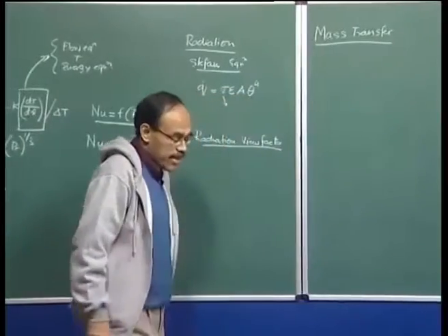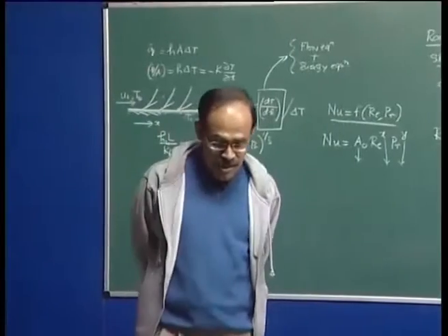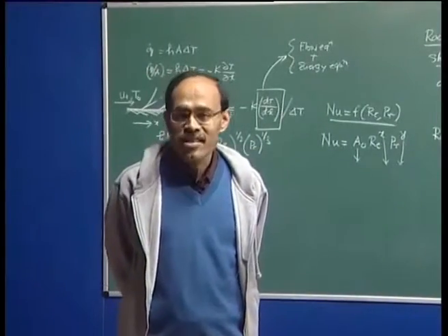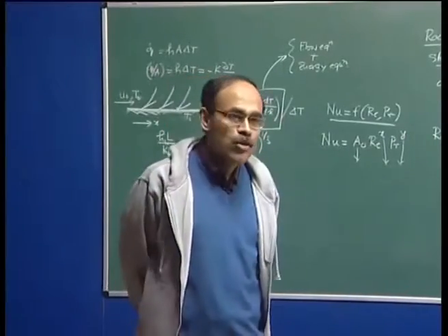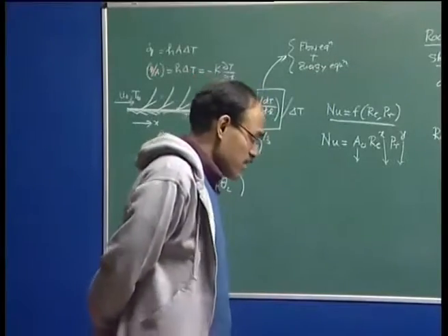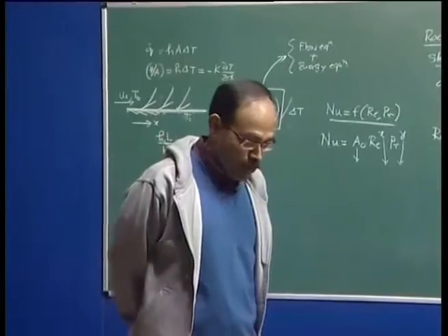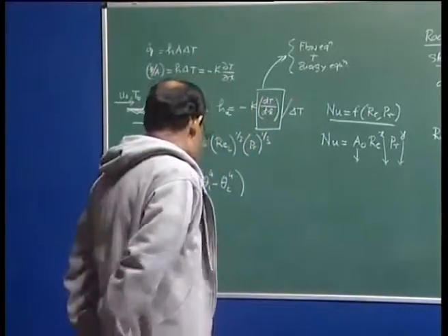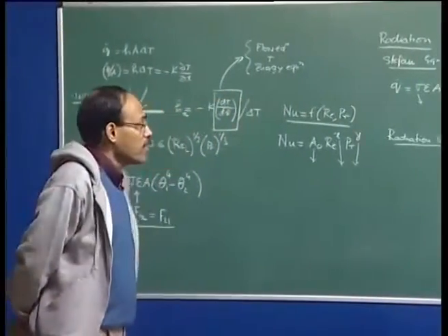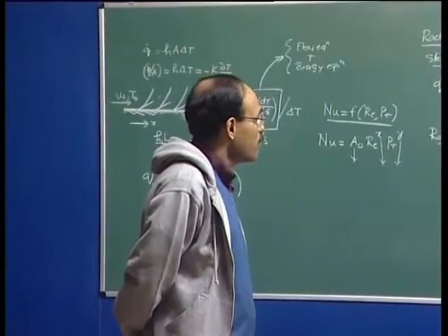extremely important in our case, because we are talking about processing operations, transfer operations where there are interactions among phases, interactions between metal and refractory, and between metal and slag, and these interactions precipitate into mass transport. And the driving force for mass transport is actually concentration gradient. More accurately, it is the chemical potential gradient that gives rise to mass transfer.